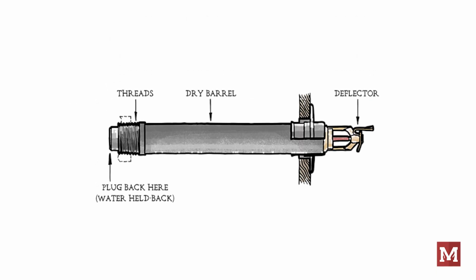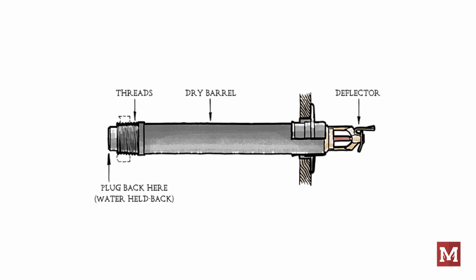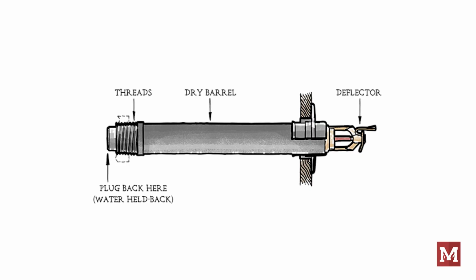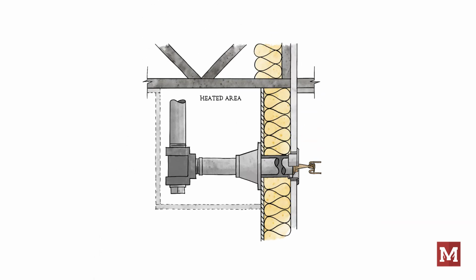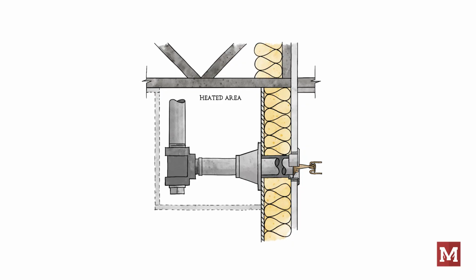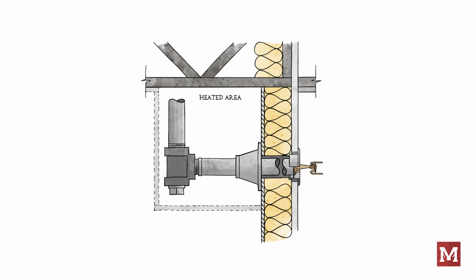We also have standard spray dry sprinklers. These sprinklers have a barrel attached to the sprinkler and typically a 1-inch threaded connection at the end opposite the sprinkler. The barrel is dry, and a linkage inside opens the end, allowing water to flow through the barrel when the element on the sprinkler is broken from absorbing heat from a fire. This dry barrel allows the sprinkler to be connected to a water supply in a warm space that won't freeze, and the sprinkler can be placed in an area that will freeze, such as an outside canopy or a freezer. These sprinklers follow the same spacing and calculation rules as other standard spray sprinklers. In other words, all standard spray sprinklers follow the same rules.